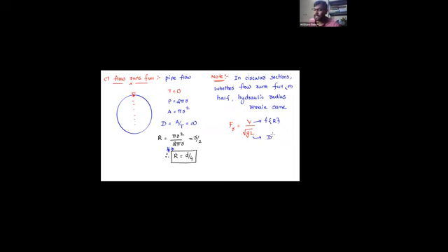See, why am I using the hydraulic radius and hydraulic depth, sir? Why are you discussing all these things? For what purpose do you need to find hydraulic depth and hydraulic radius? Because in order to classify the flow in pipe flow, I hope you remember, if you want to say whether the flow is laminar or turbulent or transition, you use Reynolds number, yes or no? And in the case of open channel flow, in order to classify the flow, we are going to use Froude's number, and we classify the flows as subcritical, critical, and supercritical flows based upon the Froude number.